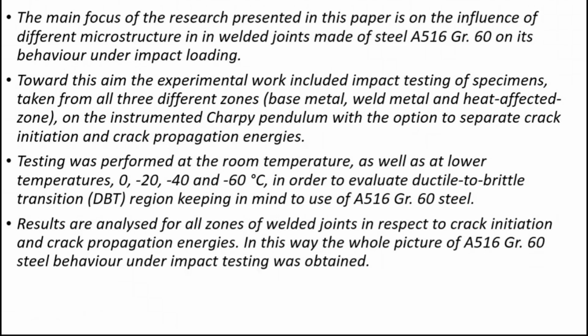Actually, our main task was to find out how these welded joints behave at -60, because there was an idea to use this steel as a pressure vessel, as a tank for liquefied CO2, which operates at approximately -60.